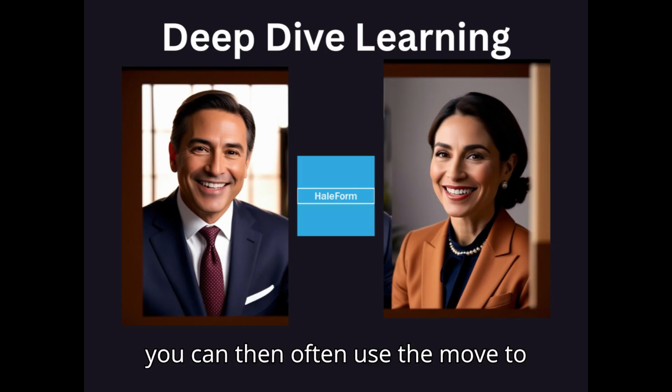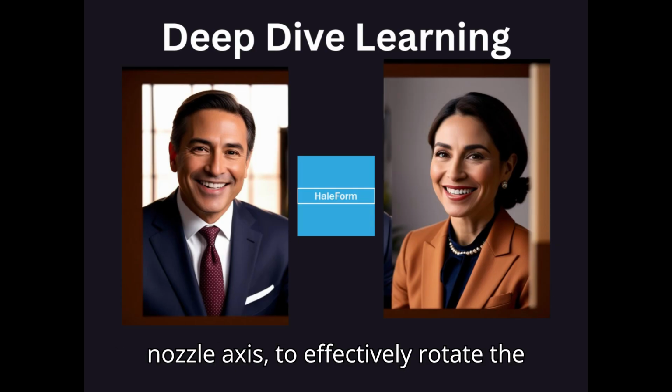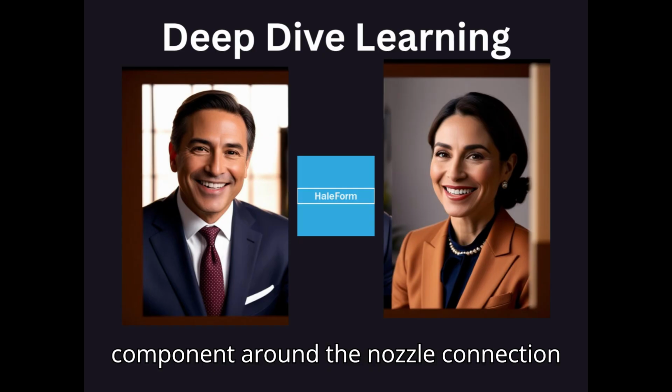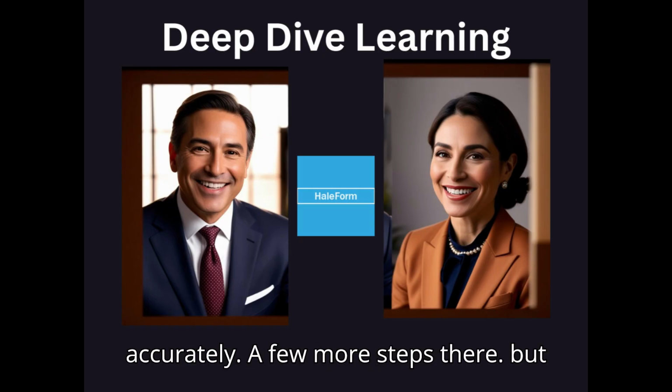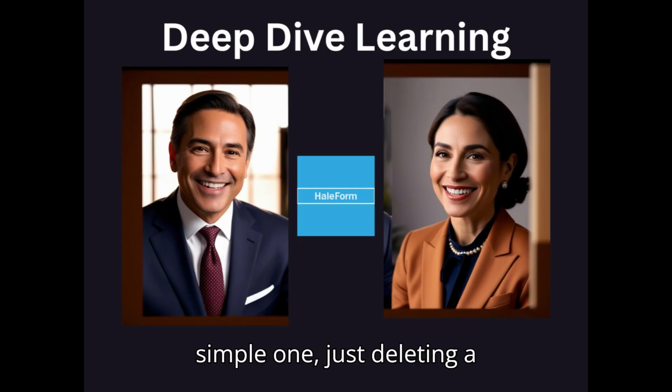Once you've locked those, you can then often use the Move To command, snapping to points around the nozzle axis, to effectively rotate the component around the nozzle connection accurately. A few more steps there, but makes sense for control. And finally, the simple one, just deleting a component.